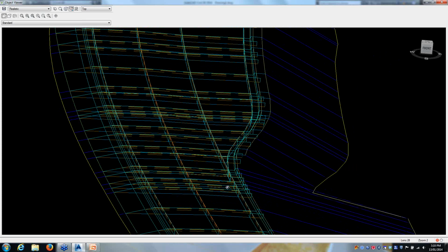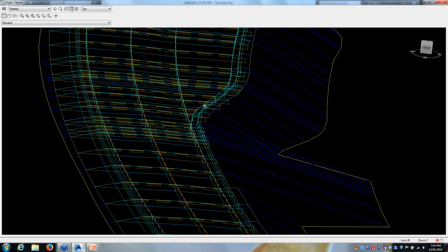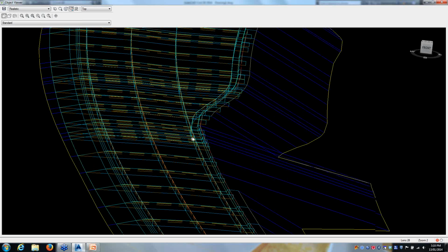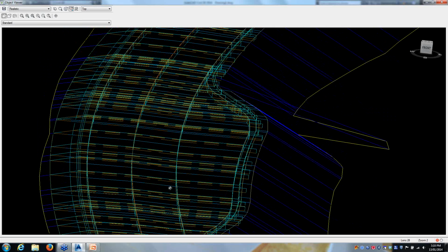And if we look closely there, you can see here's the lane, and there's the reverse and the crossfall coming back up to where the curbs are now added on, and where the alignment in the corridor and the edge of the lane come together, that stub has zero width, so that's just fine. I can handle that quite happily.